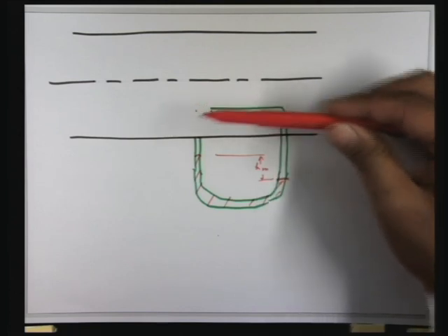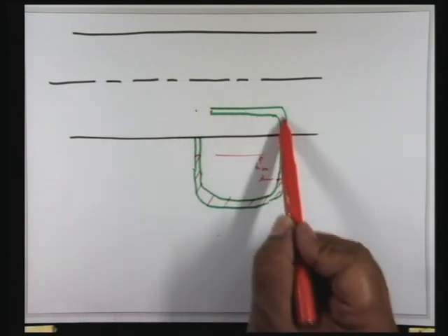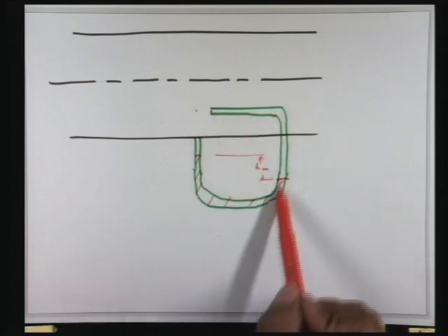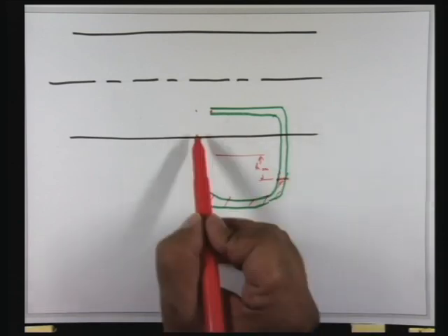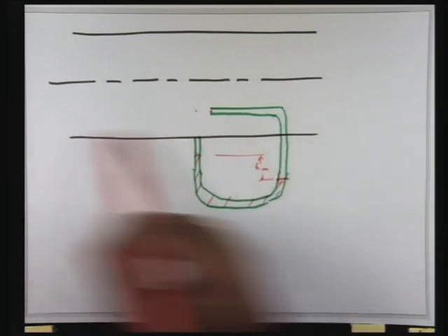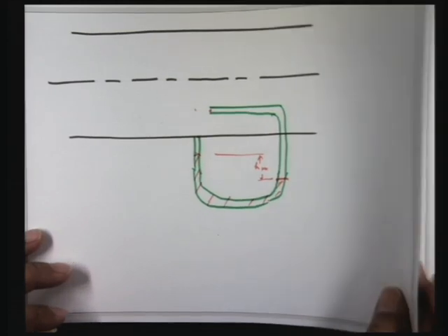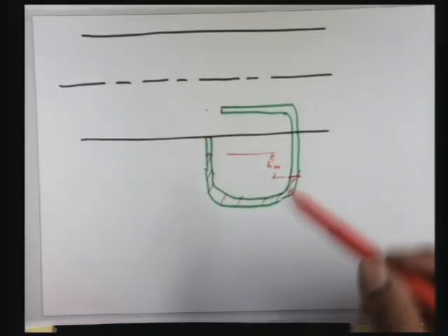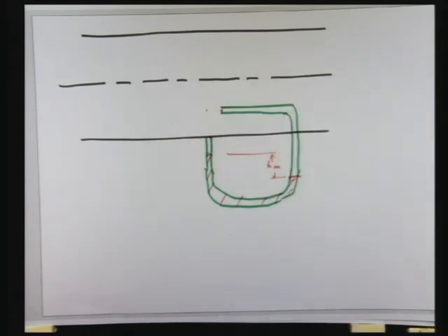The fluid which is in this horizontal tube and this vertical leg is at rest. This manometer fluid is at rest, and the fluid up to here is at rest, and here the fluid is flowing, but it is flowing in this direction. All right. Now, by inserting the tube, you are disturbing the flow, so there will be some error. You can't help it.